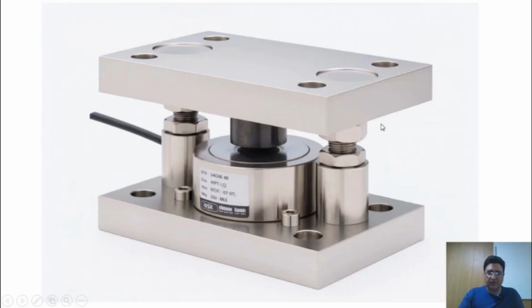The way these load cells are installed is that we use a mounting. A plate is placed under the load cell on which the load cell is mounted, and another plate is placed above the load cell, which is connected to the load cell itself by this load button. And when we apply force here, our applied force is effectively transmitted to the precise center of this load cell